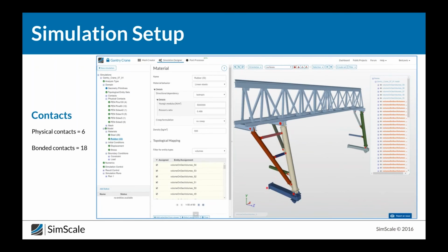So if you think of this blue member down here, this blue member is connected to a fixed constraint, and so it's stable, but then the pin that sits inside of that blue member and this column here, they're not constrained apart from the physical contact between the pin and the column itself, and so you could visualize that as maybe rattling or the pin moving sideways, and so all that movement makes for an unstable solution.